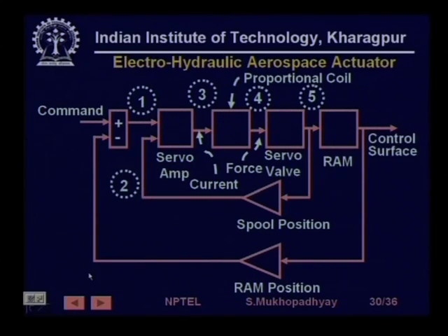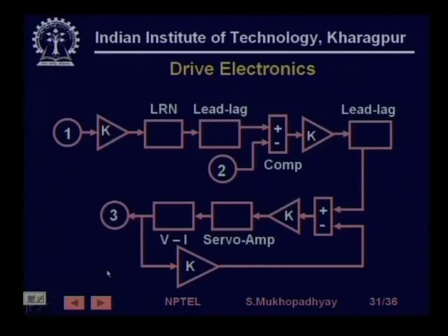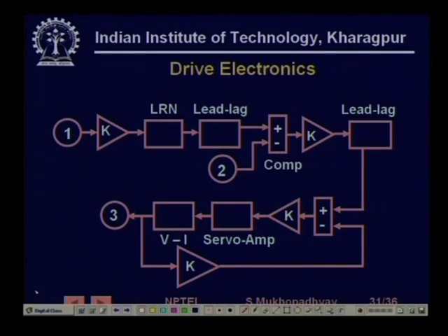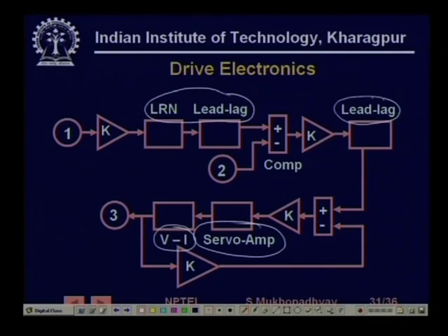We will not do it in much detail, but these are typical drive electronics. All that I wanted to show is that there are certain elements, for example, you have to use servo amplifiers and V2I converters, and then you need various kinds of filters, specifically because you want to avoid giving inputs to your system which may cause things like resonance. So, from that point of view, you have to cut out certain frequencies in your input, and that is why you need various kinds of notch filters.